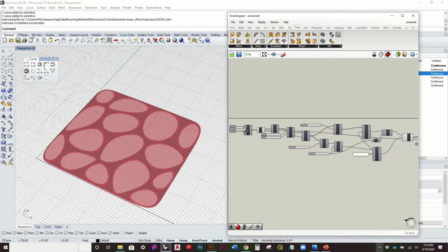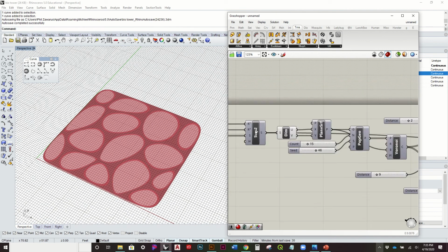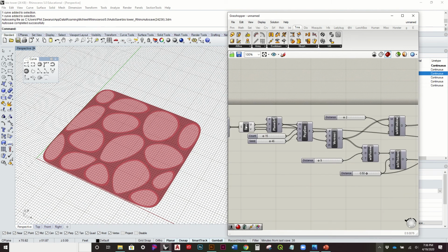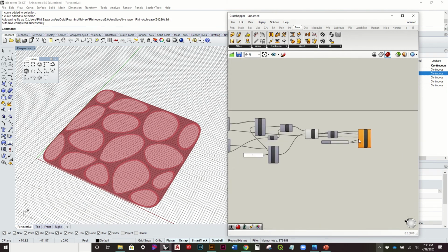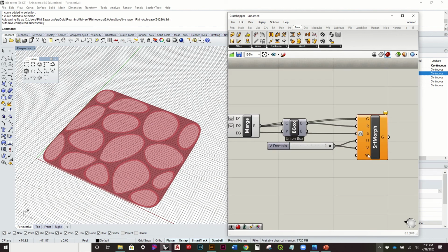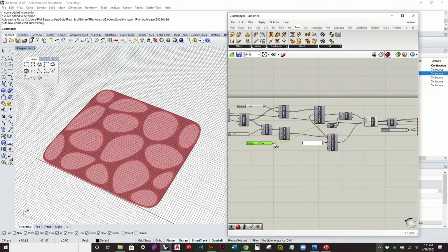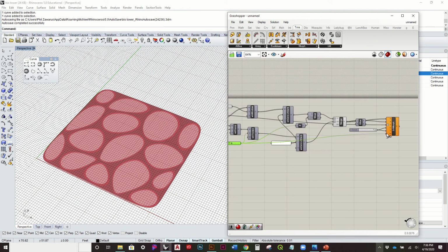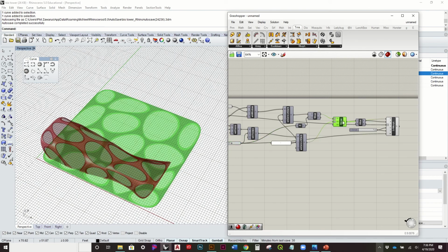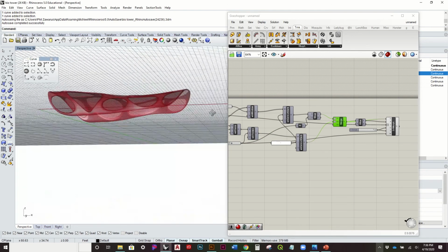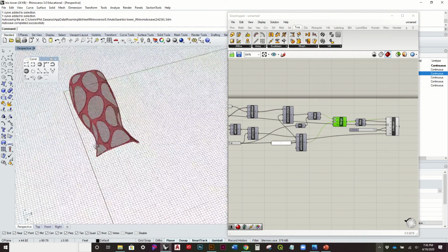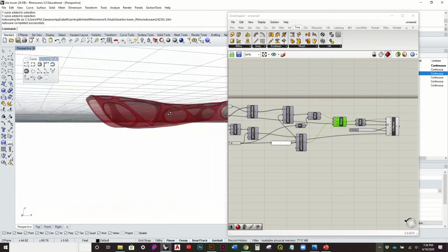That swept surface doesn't have any thickness. So you can see we don't actually have any dimensions for that. So what we use for our W, or basically our Z value, is the same thing that we use for this extrusion. So I can just go ahead and drag this over to here. Now I can turn this off, and voila, now you have that surface morphed to that swept surface.